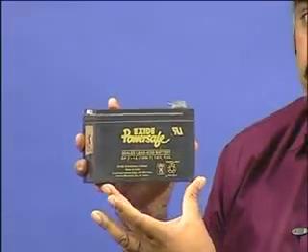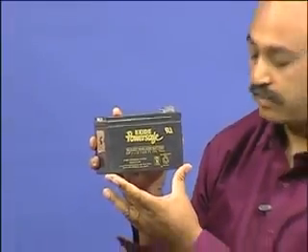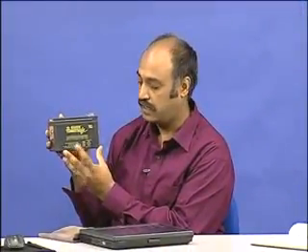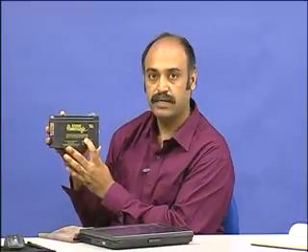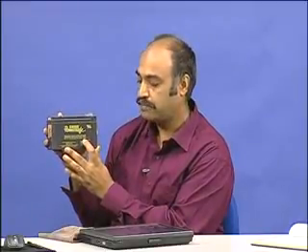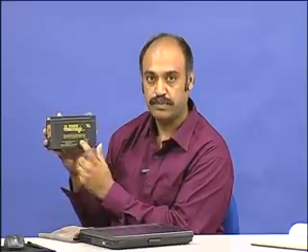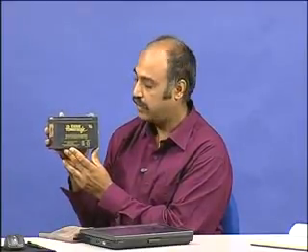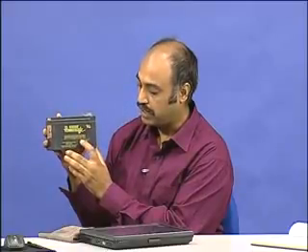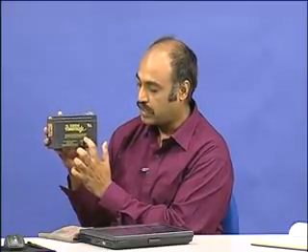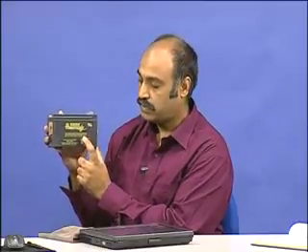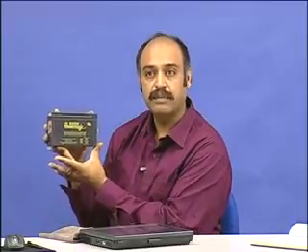Each battery has maximum discharge current capability. So for example, if this is C10 battery, let us say, then you can draw 7 by 10, that is 0.7 amps for 10 hours. So which means 7 ampere hours, something like that. So these two numbers you will have to bear in mind while designing batteries and or choosing batteries. This 12 volt into 7 ampere hours turns out to be 84 watt hours. So 84 watt hours is the energy capacity of this battery.